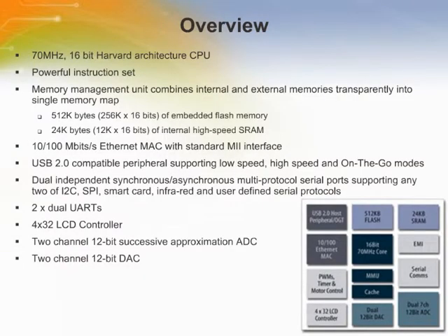eCOG1X is a member of the Cyan Technology eCOG1 family of low-cost, low-power microcontrollers targeting embedded communications applications. The eCOG1X product family is a range of low-power, feature-rich microcontrollers based on a 16-bit Harvard architecture with a 24-bit linear code address space, that's 32 megabytes, and a 16-bit linear data address space, that's 128 kilobytes.